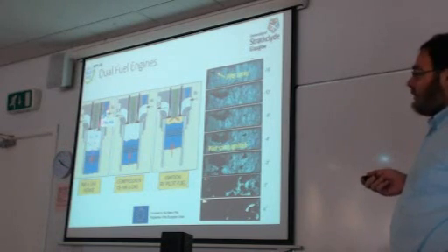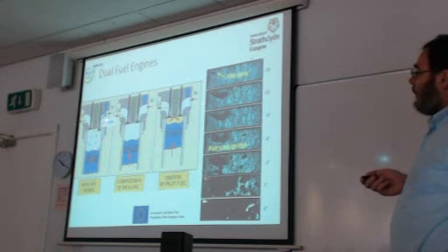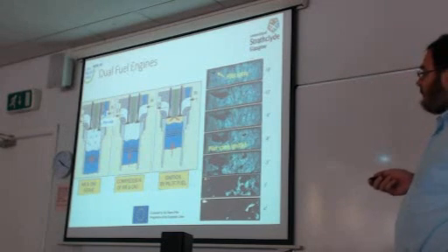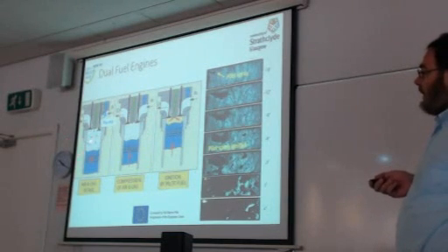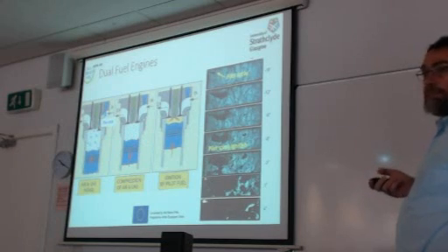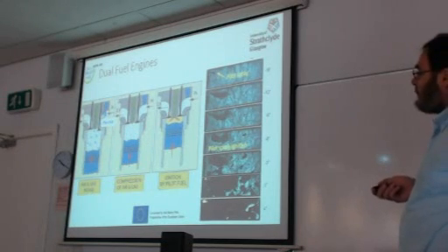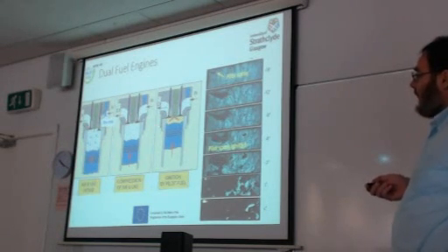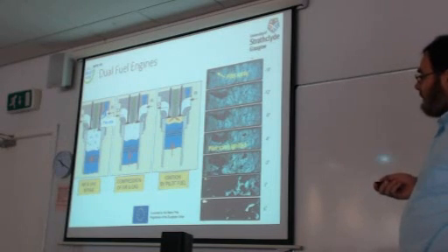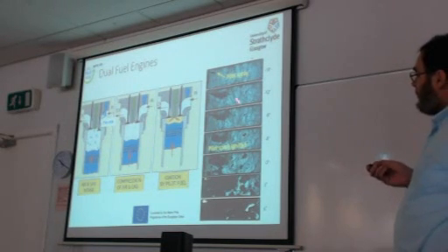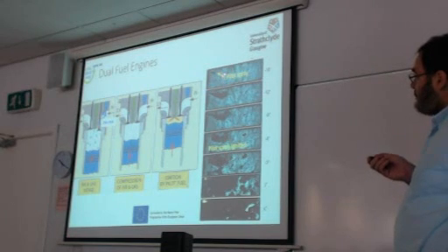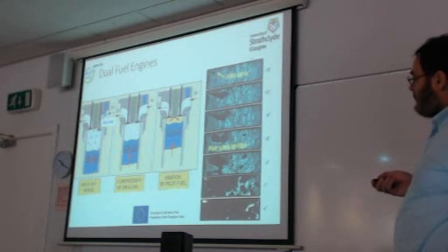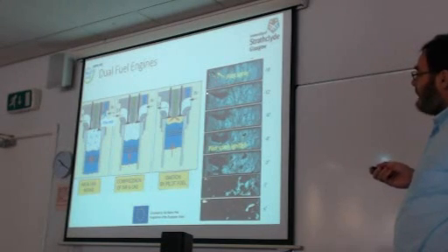So the process is that we have the natural gas injection in the port by using an injector. During the induction process, the inlet valve is open and the piston moves downwards, so that initiates a mixing process between the natural gas and the air. At the end of the compression, of course, we have a perfect mixture of natural gas and air. So the pilot fuel is injected, and that initiates the combustion. And of course, we have a premixed combustion in this case.